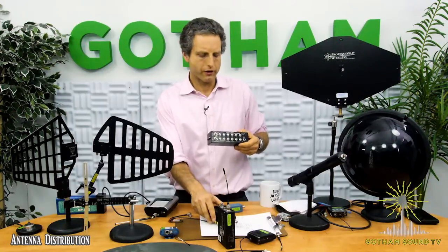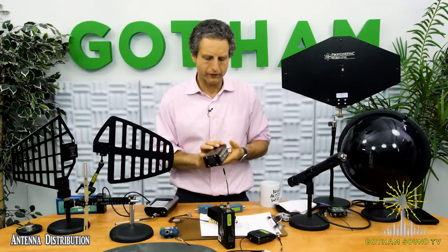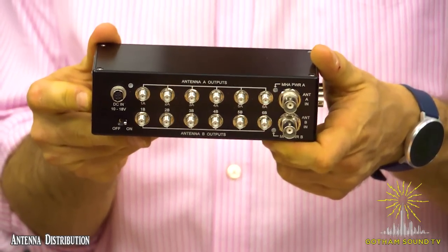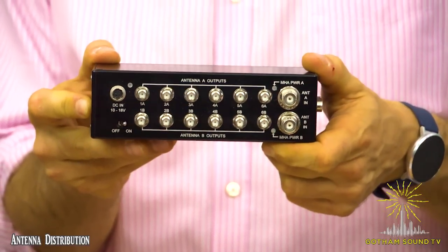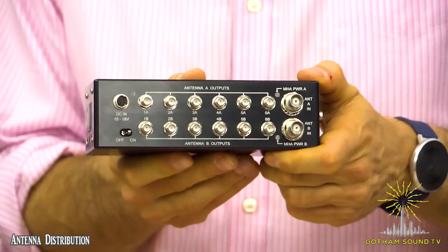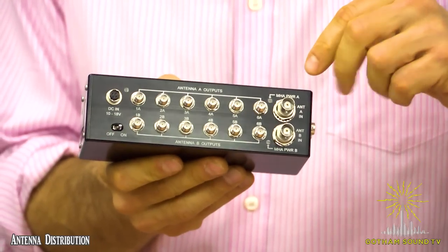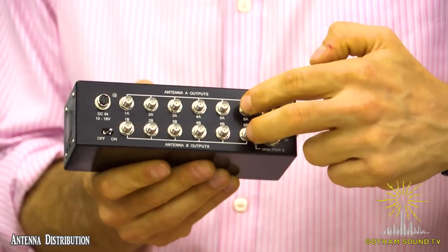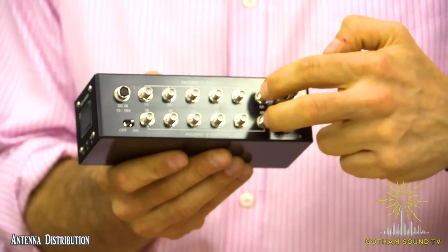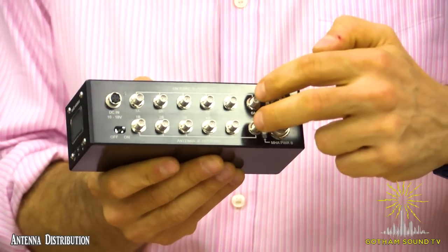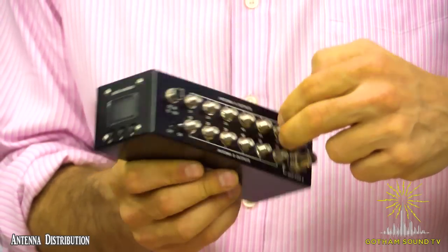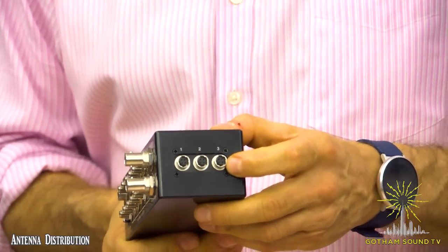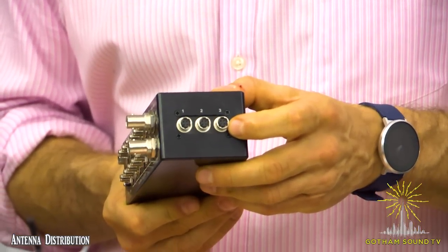And then there's another product that's relatively new to the market. This is made by Audio Wireless. It's the model DAD M226. This adds not just RF distribution, but it can distribute power through these antenna inputs to receivers. Some receivers can actually take power through the antenna inputs, but it can also power auxiliary products that way as well.